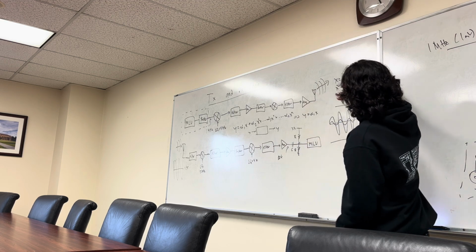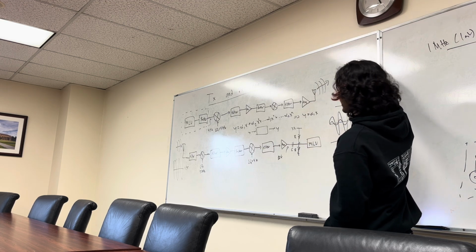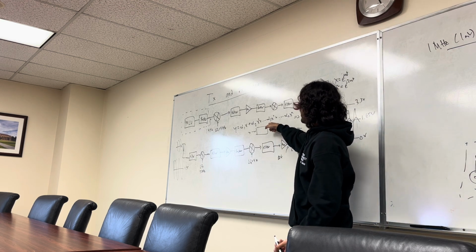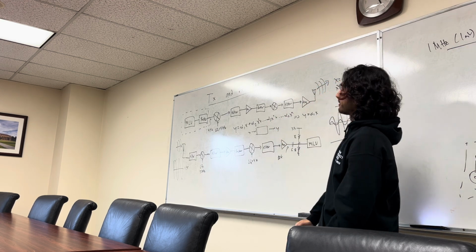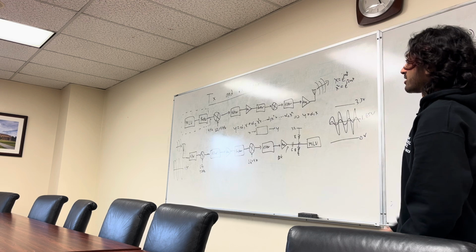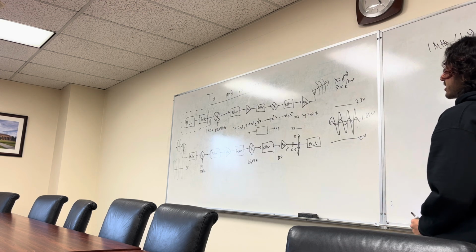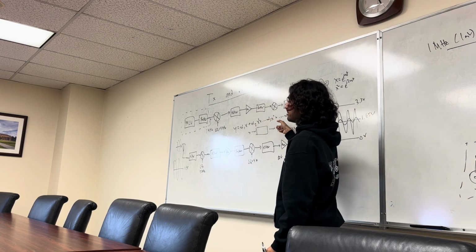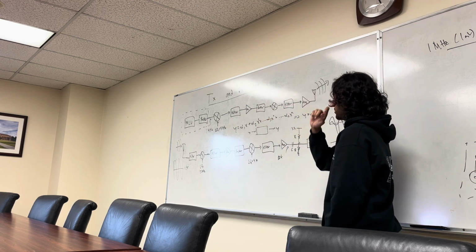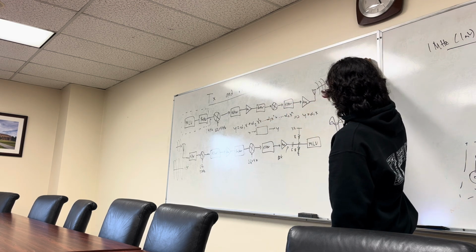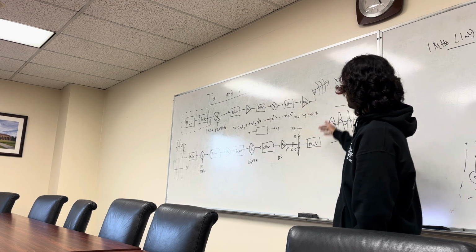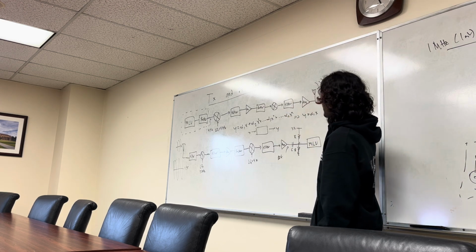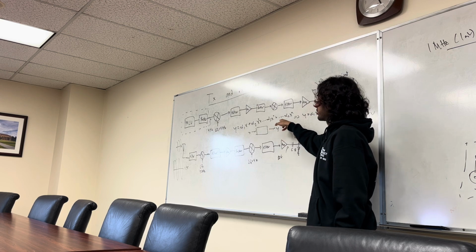So you can see that we get your fundamental, second harmonic, third harmonic, nth harmonic, all right? Now, all systems are inherently nonlinear, right? You can never get a purely linear system because you can never fully get rid of these components, but it's small enough and you can approximate it, right? But if these harmonics are large, we start to see them. If your x is large, you start to see these other higher order terms.